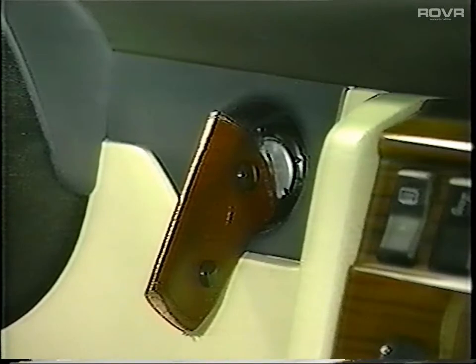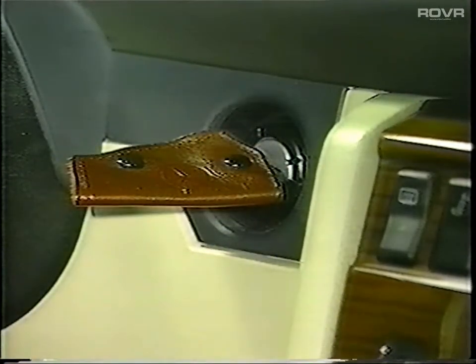It is important to remember that every time the key is turned off and back on, the lambda signal is canceled and the diagnostic signal is again locked in. The procedure has to be repeated to provide the lambda signal.